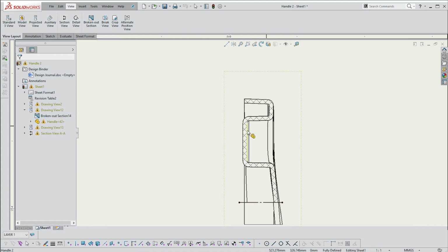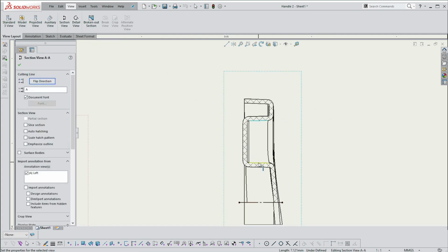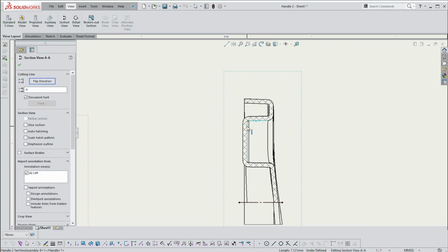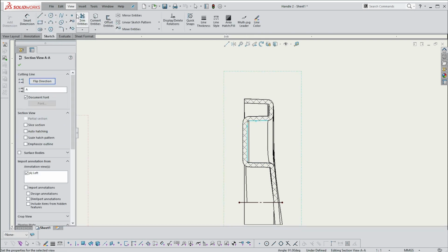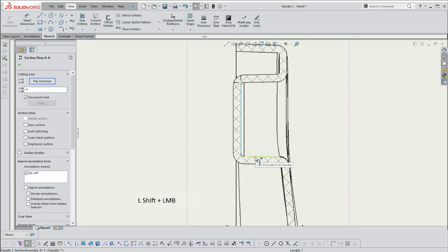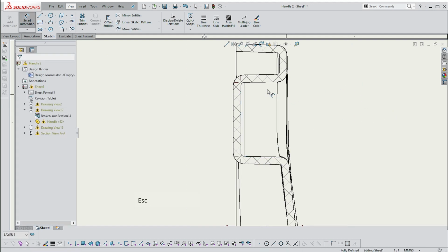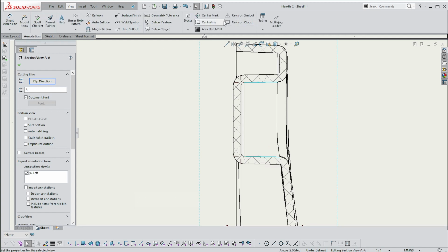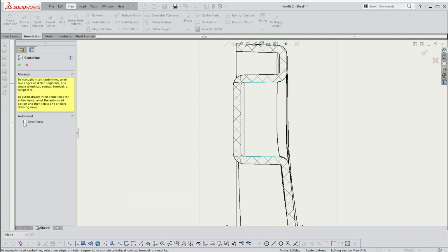All right, so we have to introduce these. So it's not that, it's line. Hold the shift button down. Okay, so that's a virtual sharp number 1. Let's just get this in place, and then that'll be virtual sharp number 2. And before we put in a diameter, let's just get a center line going. So it'll be annotation, center line, select view.